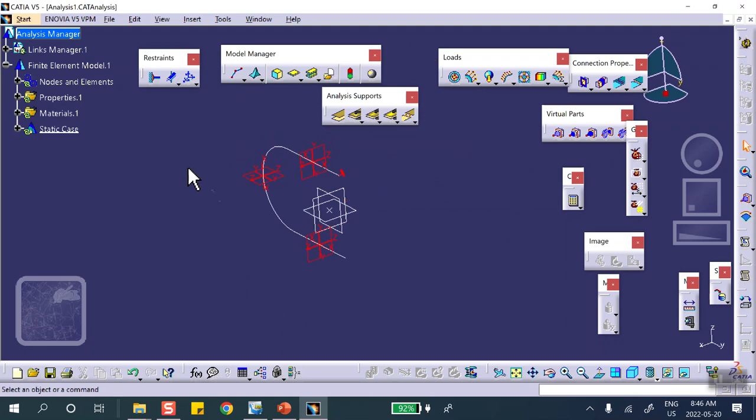By the way, let me remind you, beams, each node has 6 degrees of freedom. So when I say clamp, that means that point does not translate in direction X, Y, Z, okay, and does not rotate in any other direction. So you could have done, for example, check all 6 of them. That would have done the same thing. Good. Now we want to take this end and pull it down.